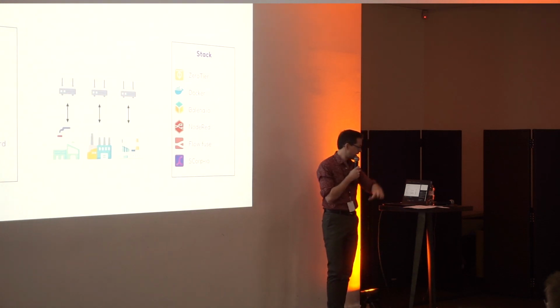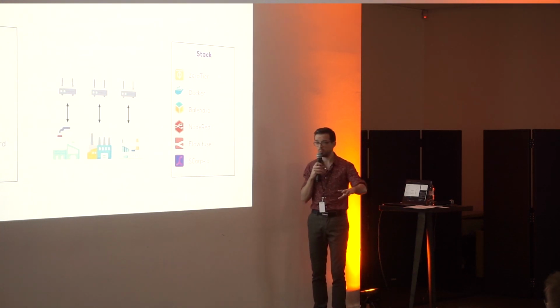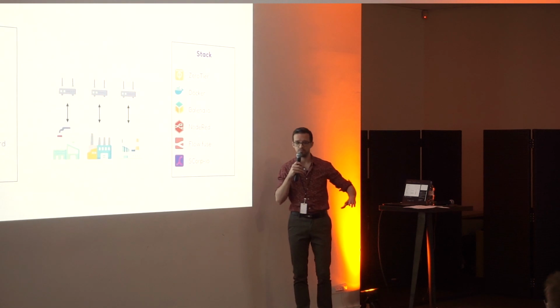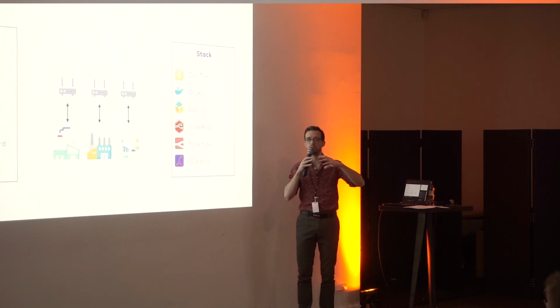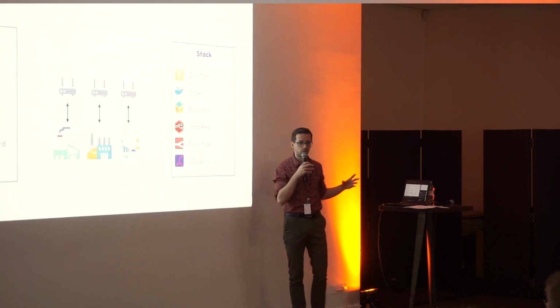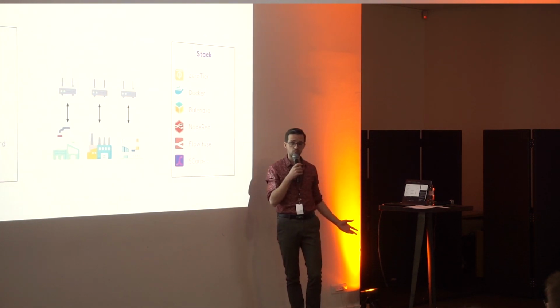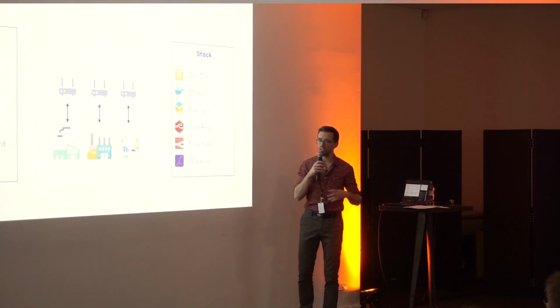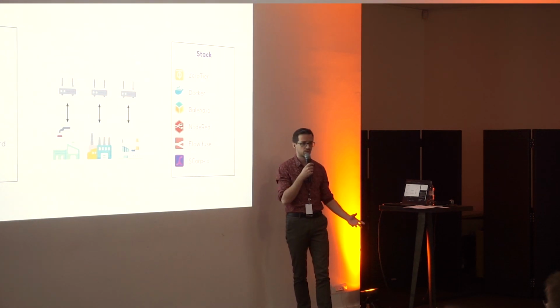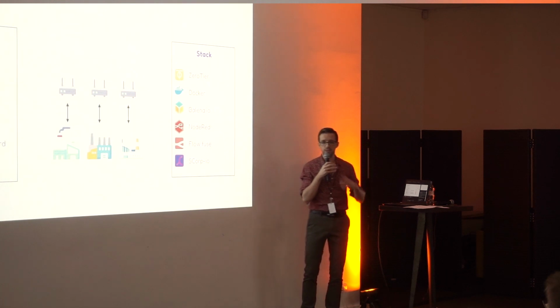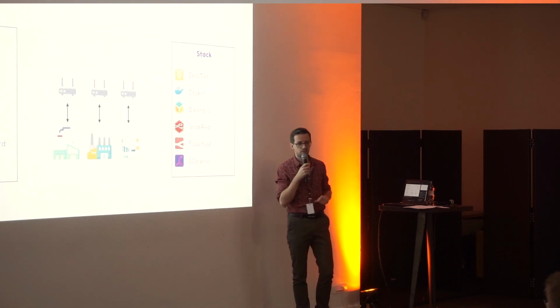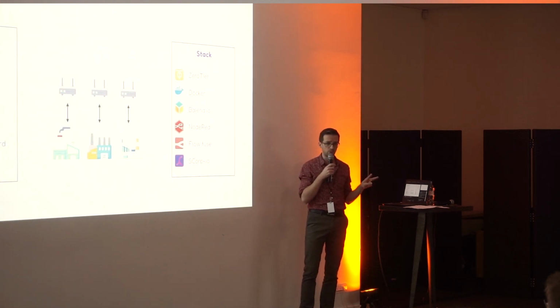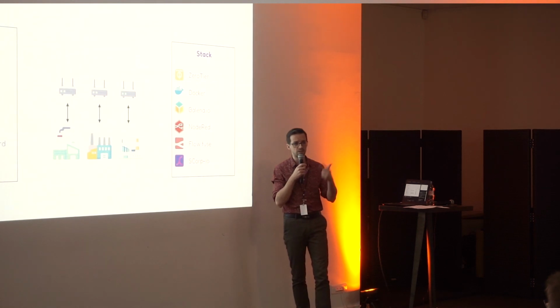So UNS is very important because it's going to make your data work together on the cloud. For me, it's better to do it on the edge, of course. And UNS is not only about cleaning your data. There are two notions which are very important: sampling and hysteresis.